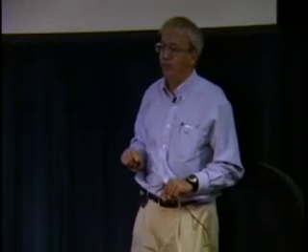Yes. So what we've done in both Imagine and Merrimac is the thing that executes the kernels is completely in order. It's a VLIW. It fetches a very wide instruction word that is 300 some bits wide for Imagine, and I think well over 400 for Merrimac. And it fetches them in order, and it has a somewhat delayed branch because of the latency of the pipe being exposed. In fact, the pipeline is completely exposed, so that if you do an operation, sometime later the result falls out the end of the pipe, and you have to schedule an operation there to catch it. And that all works just fine because you factored the surprises out.